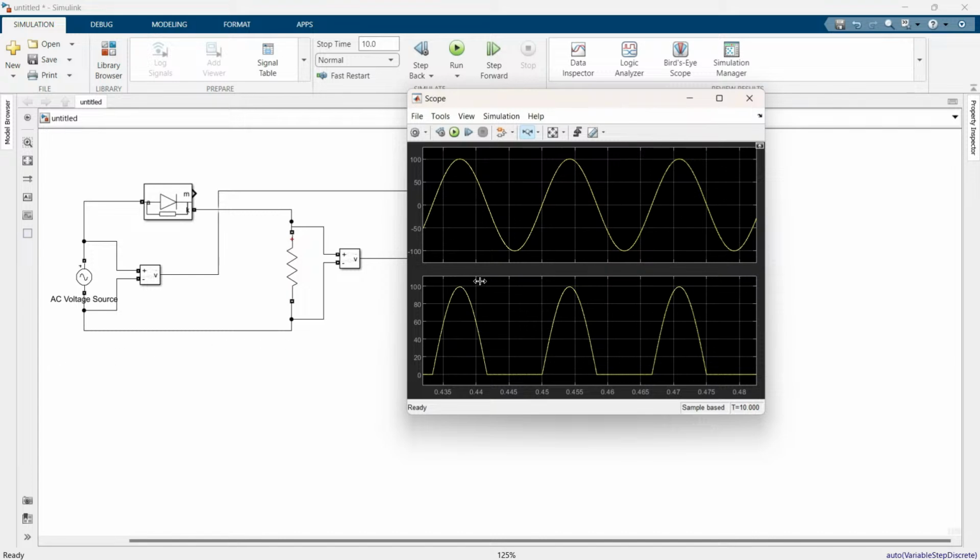During the negative half cycle, the anode will become negative and the cathode will become positive, which is known as reverse bias. So the diode will block the negative half cycle. When an AC source is connected to the half wave rectifier, only the half cycle will flow through. The output of the rectifier is taken across the resistor load.